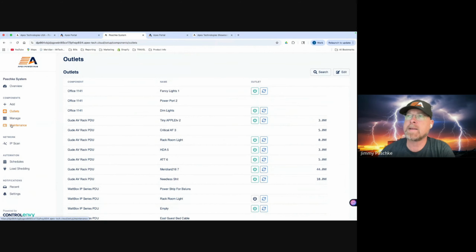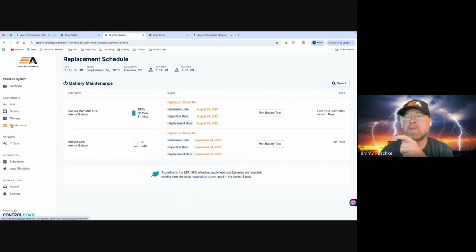Yeah. And then last thing about the UPS screen that I was on, because I mentioned that knowing the date is kind of like a BS way of replacing batteries. We do a battery run test every week. You could get notified that the battery run test failed. Then you could call the customer up and say, hey, we used math and science to figure it out, and it told us that our batteries are no longer healthy, so it's time to swap. Or you could change the dates.